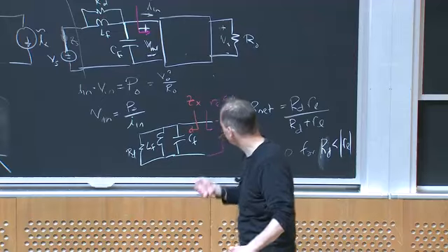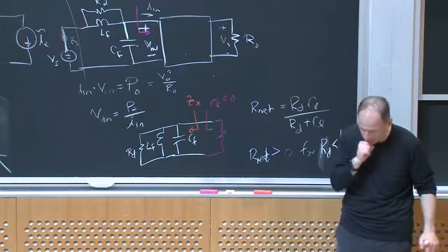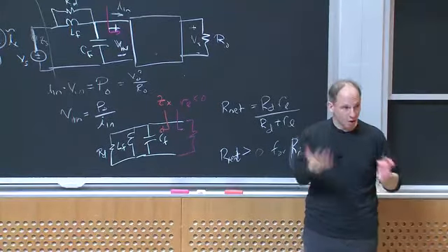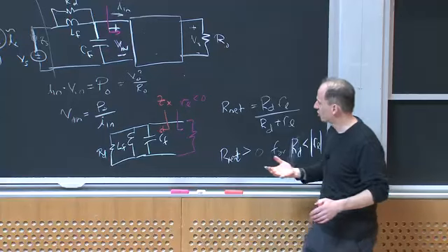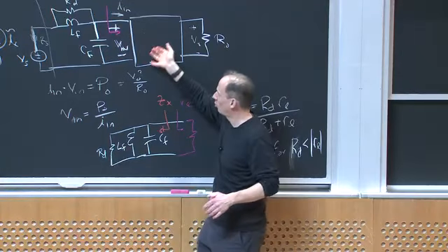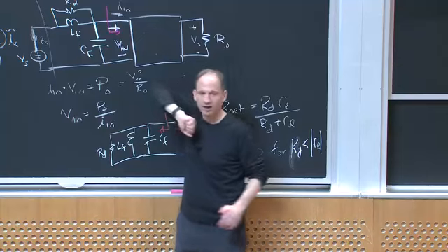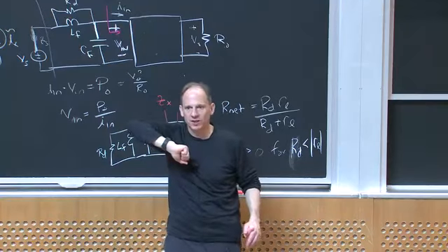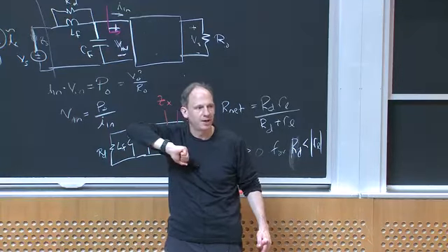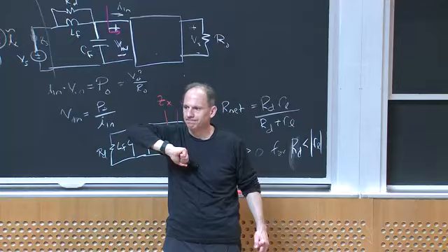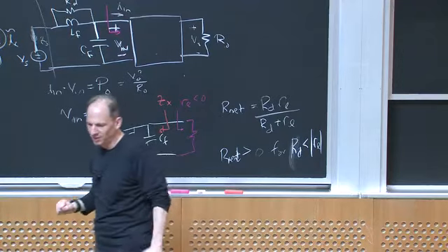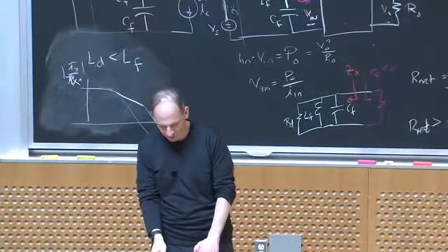But a good starting place for all that is just to make sure that under perfect control your filter is well enough damped to deal with the negative resistance of a perfect controller. So that's the place I would start in thinking about any design. So that's a little bit about filter design and filter damping.